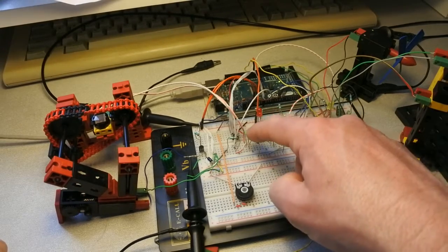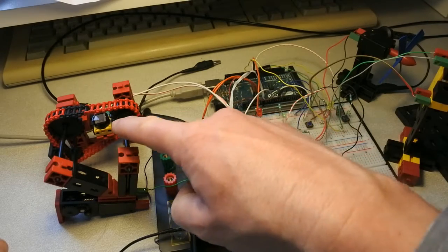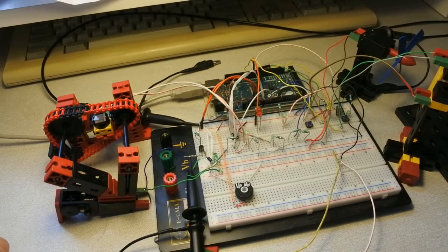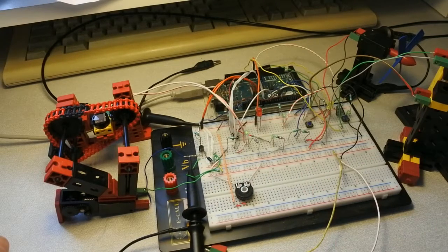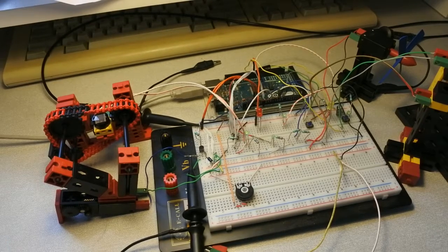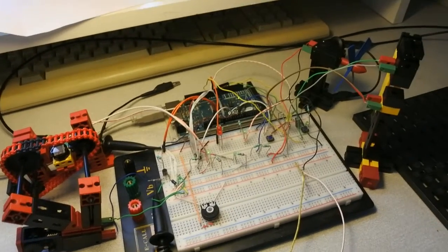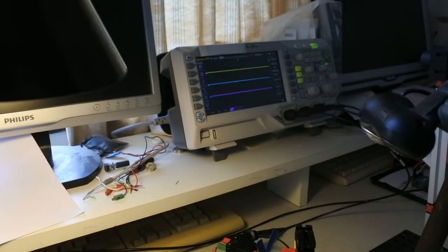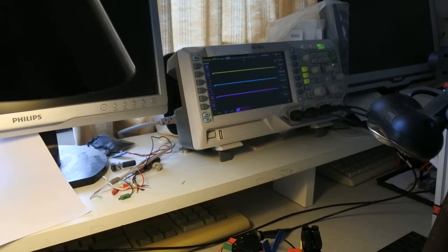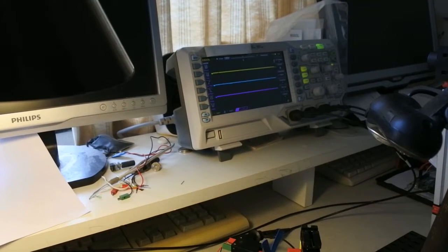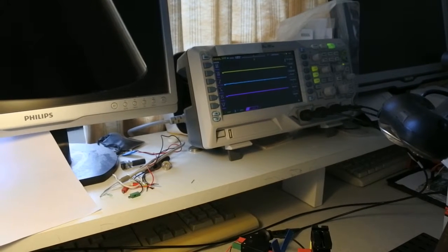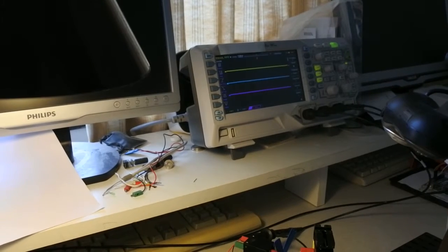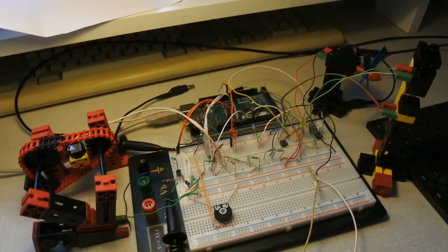So this one is not powered by the Arduino, it's powered by the LDR. Also, this LED from the transistor circuit is not burning anymore. Apart from that, when I point the camera at the oscilloscope, there's no signal at all. There should be at least pulse modulation on the yellow line as well as the blue line, but everything is absolutely quiet.